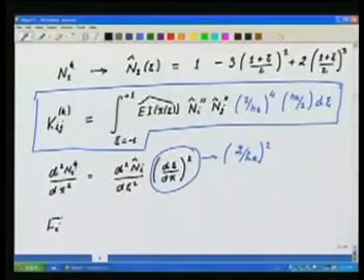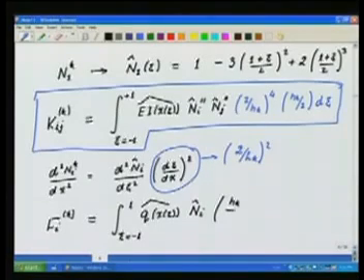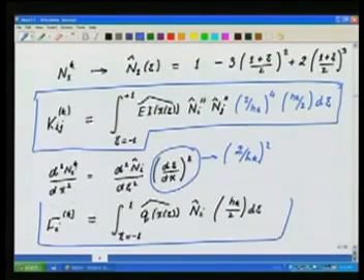Okay. Similarly, Fi for the element k will look like this: integral from -1 to +1, q becomes now a function of psi. So, I will make it q hat into Ni hat into hk by 2 d psi. So, the element load vector entry becomes this.